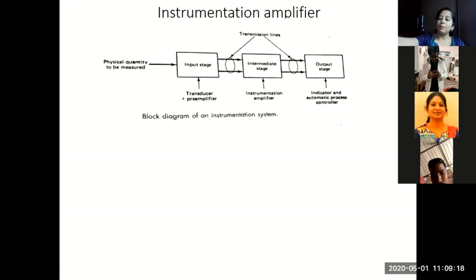So even from the place where the temperature is measured, from the furnace to the central control room, through a wire, noise would get added because the signal is very small in amplitude. Since the signal is too small in amplitude, it would be merged with noise and it would be very difficult to separate the signal from noise. Okay. So what we do, along with the transducer, the measuring device.